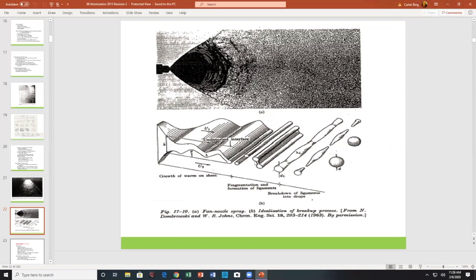That's quite interesting. Here's another view from Robert Brodke's book. You start with a sheet, and the sheet thickness is, again, very important. Sheet thickness tells you the drop size. It indicates what the drop size is. What happens is you have, again, the waves in the sheet that break up into ligaments. The ligaments collapse down into one large ligament. Here is an interesting point.